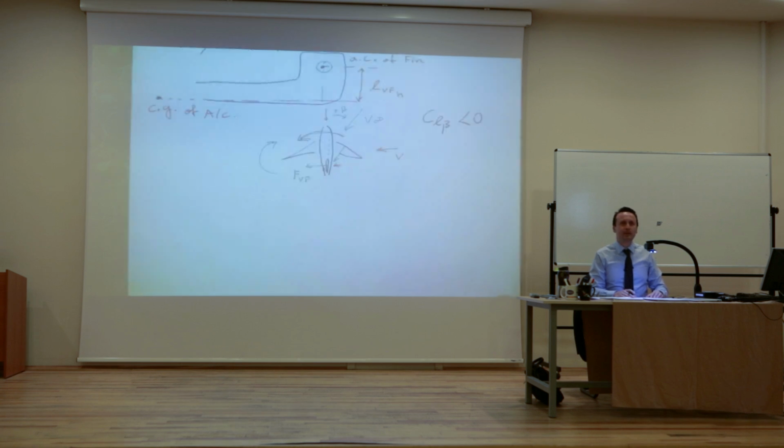All right. So stability and control, they move in different directions. Because in order to go away from the stability, from that equilibrium point, you need to have control. So in other words, yes, if there's a disturbance, you will come back from your side slip or from your roll angle. The question is, sometimes I really want the roll angle, right? Why do I want the roll angle, for example? To turn, right?